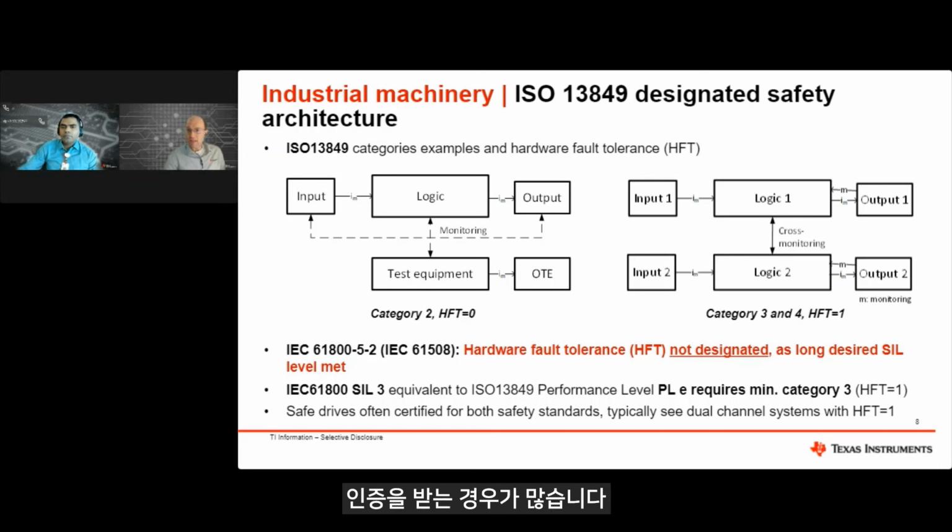To save BOM and space, one of the safety channels can be integrated into the control MCU, which now becomes a safety MCU, as shown in the middle column. We have two assessed concepts based on C2000 MCU for both use cases. The third architecture on the right now moves both safety channels into the communication and control MCU respectively. For systems like industrial robots, which typically always require functional safety, it offers a further path to BOM cost and space reduction. What safety features and diagnostic coverage do C2000 MCUs have, Ashish?